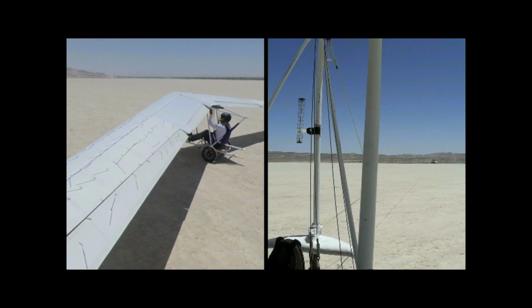First, a little intro here. We're looking at me sitting on the lake bed here. We're towing with my truck, and if you look closely at the right screen, you'll see my view going forward, so you can see the airspeed there, and you can see the tow line going out to the truck. You'll see that we're using a Y bridle, which wasn't working properly, which caused some of the problems. It's supposed to tow through the CG. We were actually essentially towing from the nose of the pilot's cage, which was causing a nose-up pitching moment. And that nose-up pitching moment I had to counter with down elevator, which is problematic for my glider.